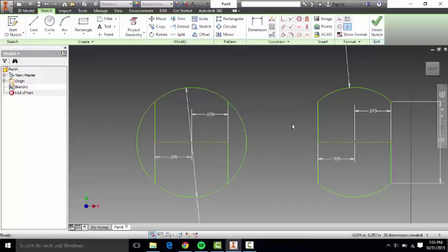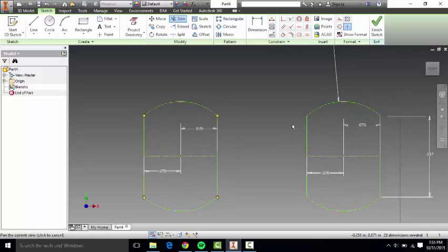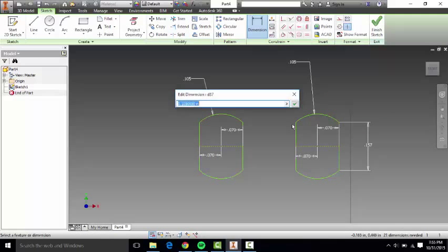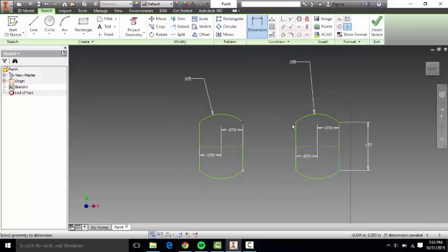And the last thing we need to do to finish this off is to get rid of the extraneous part of the circle we don't need. So we can click the trim button and it will delete everything up until the intersection of this circle and a line. Do the same thing on the other side. Now we have the DC motor slot. And you can see that this has a radius of 0.05 because we designed it that way. And if we measure this, it should be 0.157, and it is.